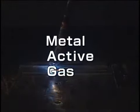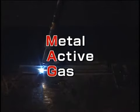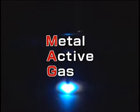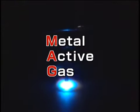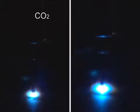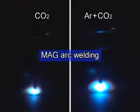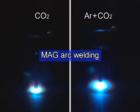The MAG welding process is an acronym for metal active gas. MAG welding is defined by JIS as using an active shielding gas in the welding process. Therefore, when welding with 100% CO2 shielding gas or when welding with a mixture of argon and CO2 shielding gas, both are considered MAG welding processes.